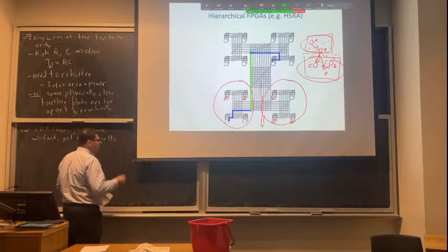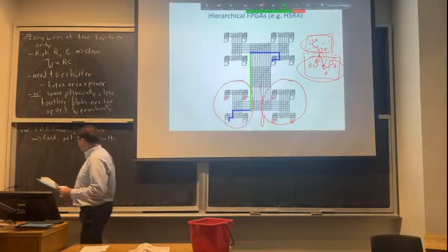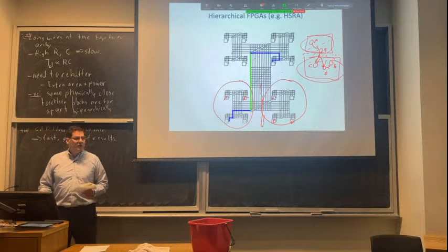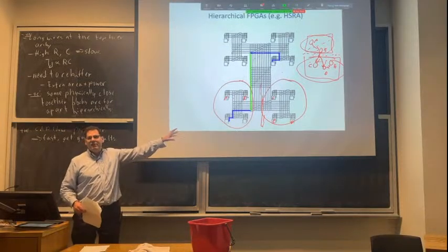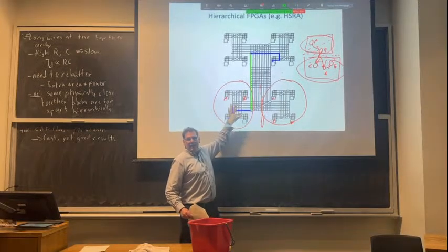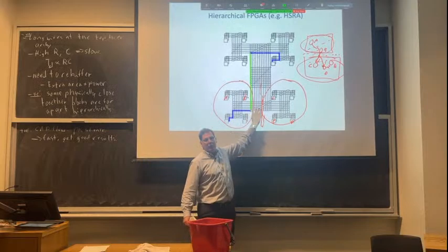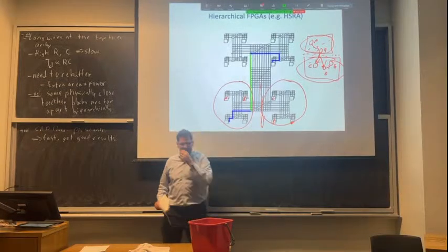And that's one of the reasons people like this kind of architecture. That advantage, though, is generally not enough to make these the best architectures, at least for big FPGAs in state-of-the-art manufacturing processes, because of these really long wires. That's kind of the Achilles heel of this.